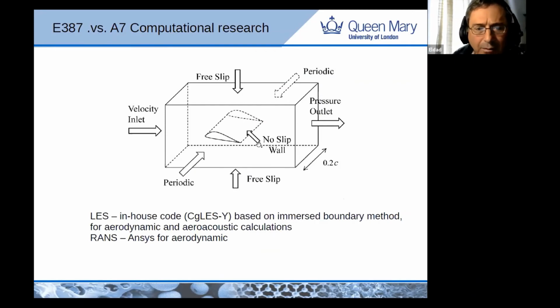We also used our own code. So this is the Y code that General Fusion used, but we put it together with our own flow solver. We call it CGLSY, and it is based on CGLS, which is based on finite volume, with quite standard LES there.